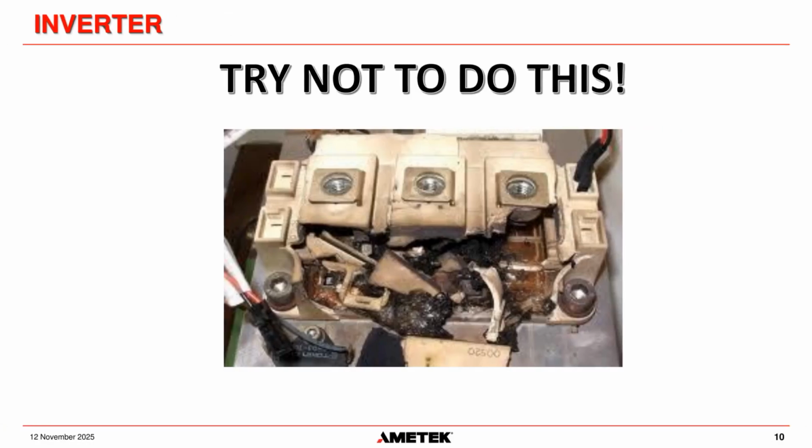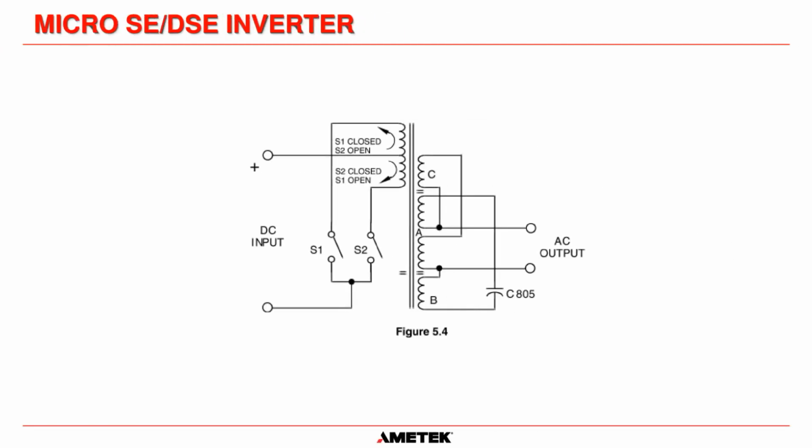And that's what they should not look like. That is the inside of an IGBT that has been catastrophically damaged. That is one of the downfalls of IGBTs: although they are getting more and more robust as technology moves on, they can be very sensitive to extremely high current, in other words, short circuits on the output. So we have to come up with ways to protect the IGBTs from basically self-destructing. And we do quite a good job of it, but we definitely don't want to see an IGBT like that inside your inverter bridge.